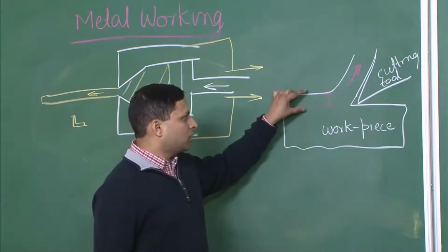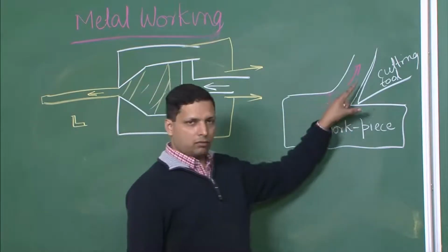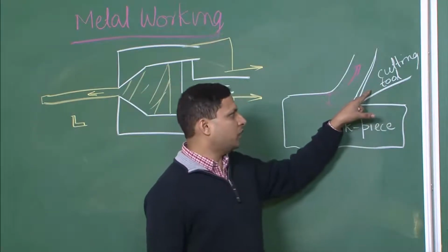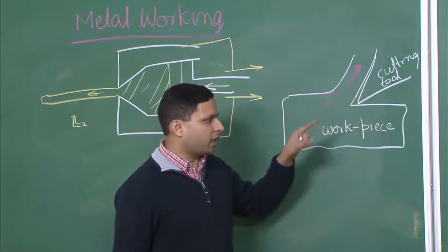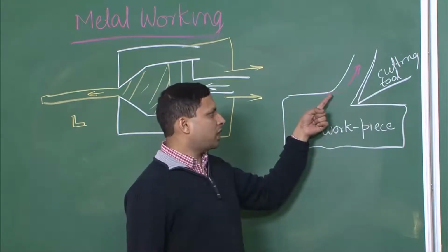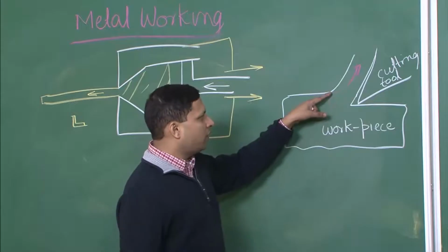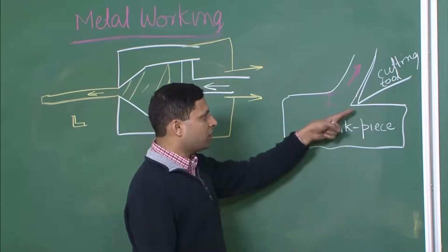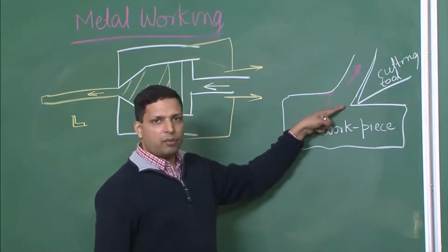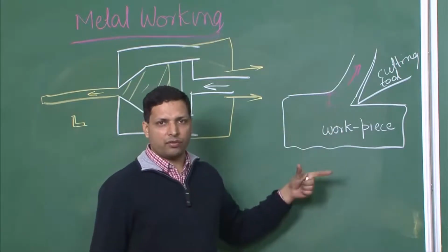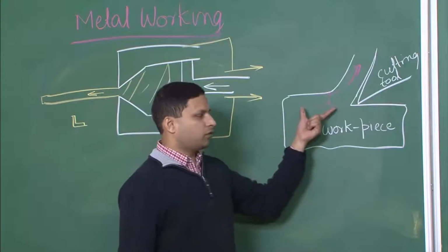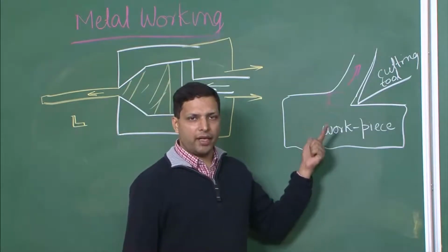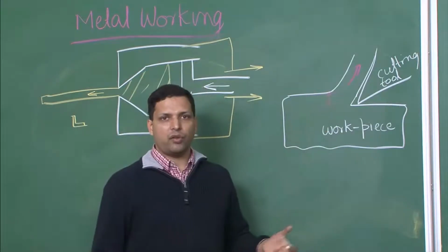Again, not only how much load will come onto the cutting tool, which will determine its life, but also the strain rate and temperature will be different depending on the machining configuration, and because of that there will be different microstructure on the surface leading to different properties, and for that we need to be able to predict the strain rate and temperature.